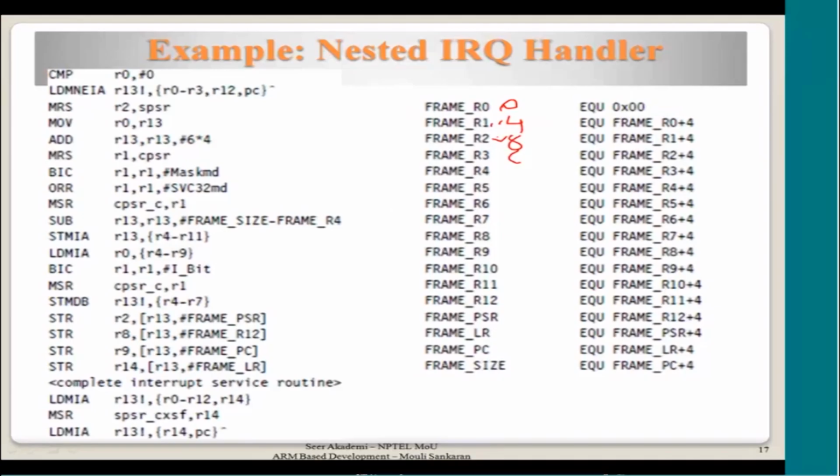So effectively, these are all the different register values. They are nothing but R0 to R15. R12 is there, then we are using PCR. R13 is not saved because R13 is a stack pointer, and we are using R13 to increment and then store the values in the stack. So we should not save the R13 inside. This is the order in which they are saved. These are constants used for accessing them. So don't worry about this definition. This is only a constant definition. But I will explain in the source code, then you will understand it.